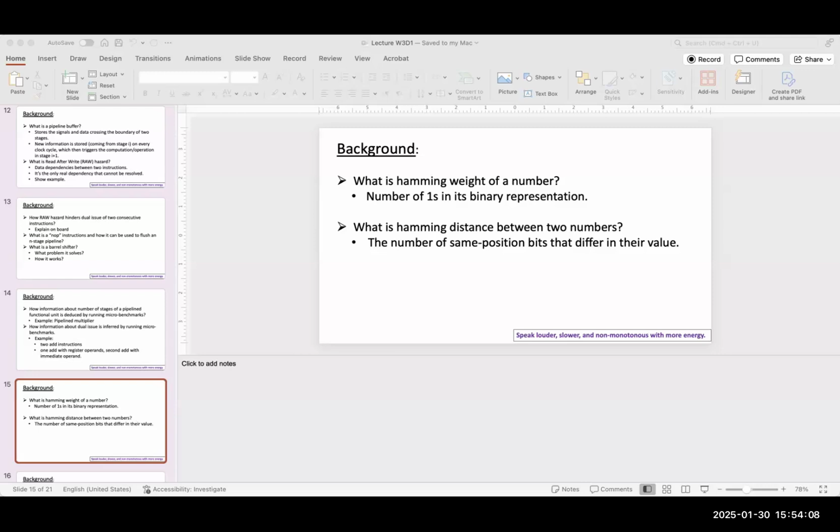Because they were able to tell by looking at how many ALU instructions can be issued. I can issue two of them, but only if one of them is immediate. So it means that there are three register outputs crossing from the decode stage into the issue stage, and one bus which has the immediate number going into the subsequent stage, right?